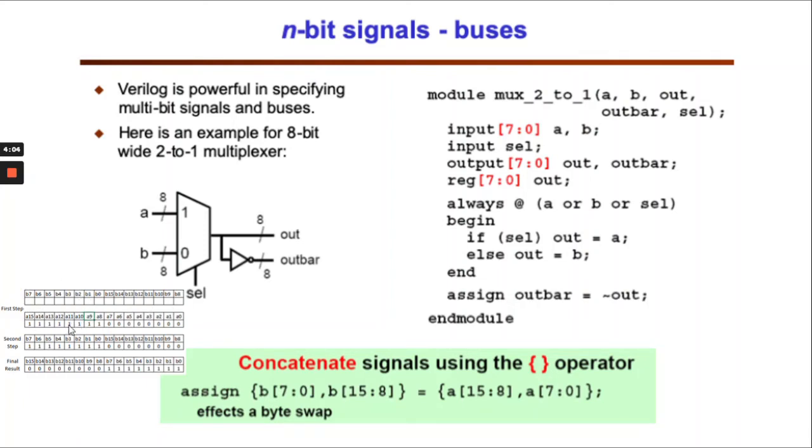And then after we assign the value, this is how it looks, right? So now B0 until B7 becomes all 1, and then B8 until B15 becomes all 0. And then if we sort it in order, which is the final result, we're going to see the value is swapped, right? For example here, it should be 1, 1, 1, 1, 1, 1, and then 0, 0, 0. And then now we are swapping it. So for the B value, it starts with 0, 0, 0, and then 1, right? So this is how you can utilize concatenate assignment here.